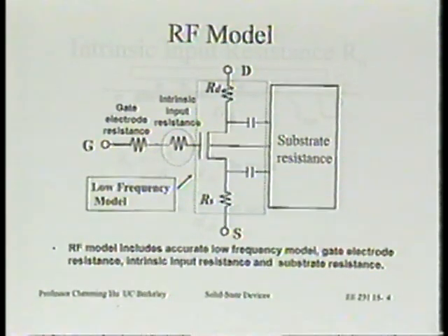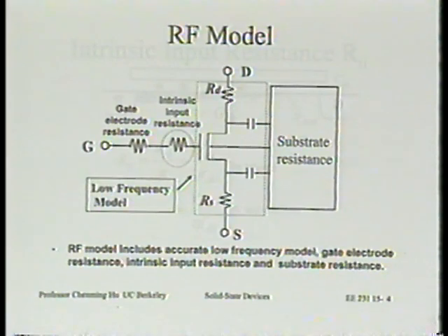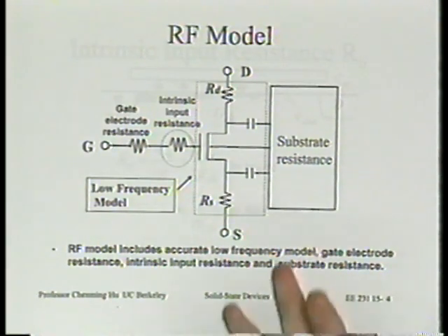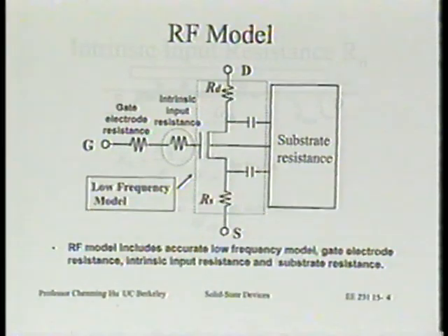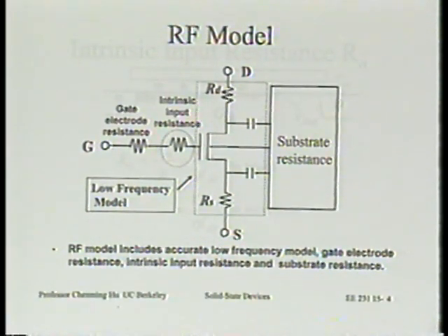Table also has the disadvantage in that you will not be able to filter out bad data as easily as you can do with a physical analytical model. In other words, it's true that especially in cases like RF where measurement is very difficult, you can imagine if you don't have a model, it's going to be very difficult to just have very clean data, and you don't know whether the data is really that accurate or not. So there's a lot of reasons to want to make the SPICE model work for RF circuit design.